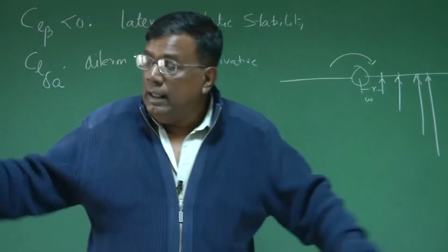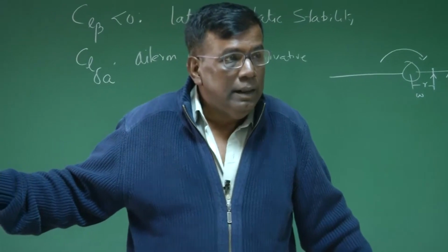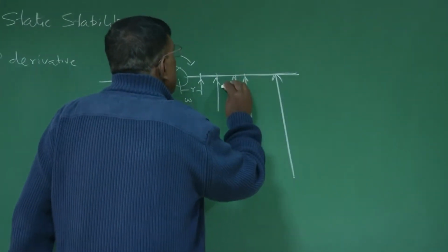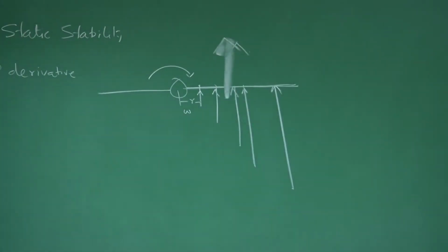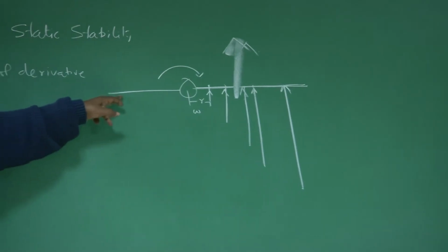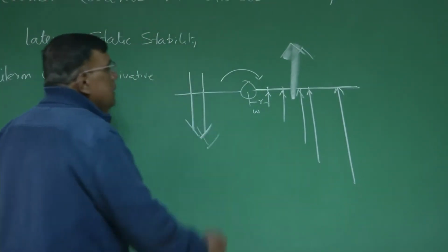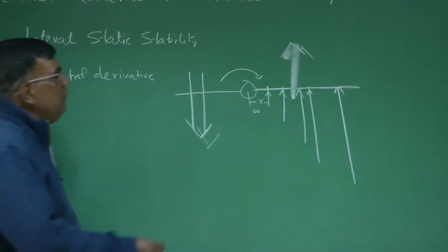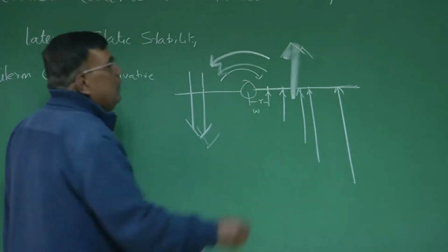It means the right wing will see an additional positive angle of attack, so whichever wing is going down will experience a force in this direction. A similar thing happens in the opposite direction on the other wing, which will experience a force in the opposite direction. What this will do is try to counter whichever way you wanted to rotate it.